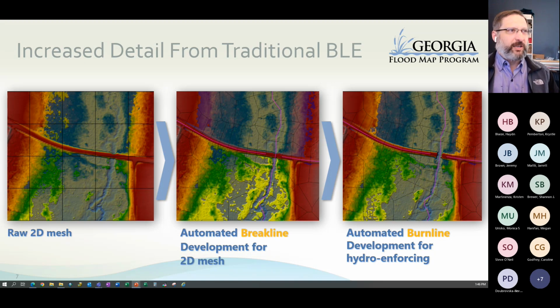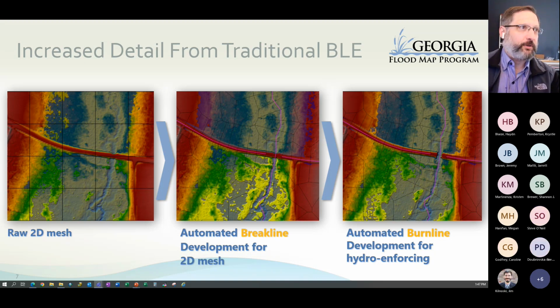Remember the little squares there, and behind it you see the LiDAR, and through the middle of that LiDAR, you can see a road. Now, remember I said computations occur at each of the faces. So that very middle square, and I don't know if Jarrett can point to it or not, there are several squares, not that one, yep, those two right there. The road is in the middle of the cell. So when the cell does a computation across those faces, it doesn't even realize there's a road there. So that will cause the floodplain not to be as accurate.